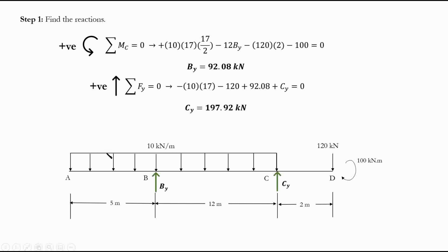Now, you might think that I can start from here and find my deflection and rotation, but the problem is my compatibility conditions. I know that at point B, I have a roller, or a pin. At points like this, I know my deflection is 0, unless there's a settlement. I may consider that there's no settlement. My deflection at the supports is always 0, basically relative to the beam.